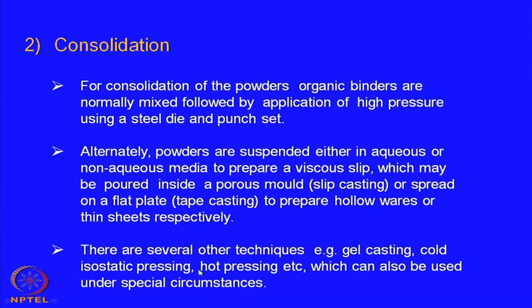Besides cold isostatic pressing, one can also use hot isostatic pressing. You apply isostatic pressure and at the same time heat the material to a high temperature.